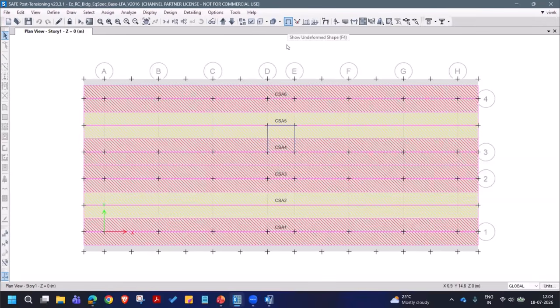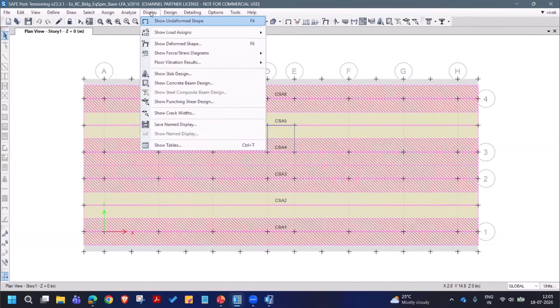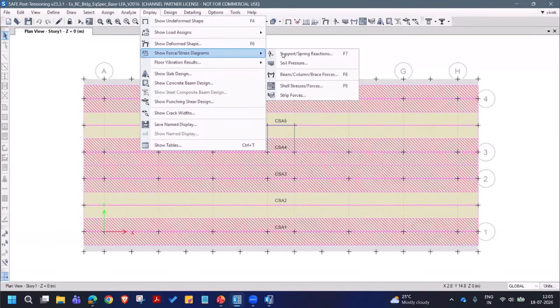So this information is utilized in the punching shear check with this dimension, and then D by 2 will be added. If this information is 0, then D by 2 is directly from that column joint. It could be incorrect, so it should be updated accordingly if needed. All right. I've taken up the raft since I wanted to cover the import option. We'll switch to an isolated footing as well as a combined footing shortly.